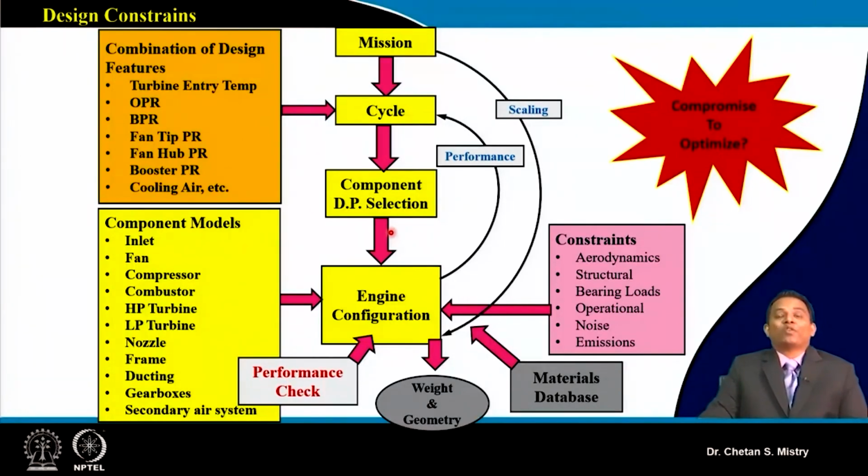But that is based on the understanding of the group of people who are working on it. Somewhere, at some point, they need to check. Suppose we consider the expected turbine entry temperature has to rise. Now the question will come, what needs to be done? How do we address this issue? You need to look for a different kind of material, or maybe some coating. That is what we adopt with the new technology. Now that new technology needs to be tested, and once we build the confidence, only then will we apply it for the development of the engine.